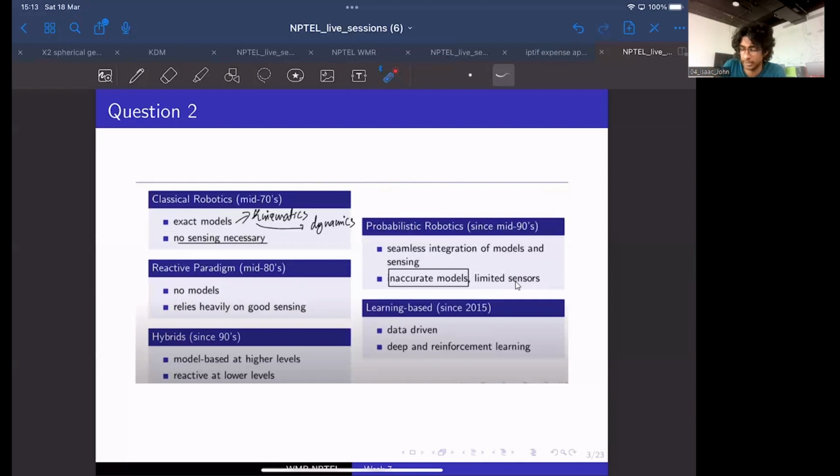So if we want the robot to follow a desired trajectory, and the robot is giving you an actual trajectory, there will be some differences between the desired and actual, right? The feedback from the robot is taken back so that it can be compared with the desired. The difference between the desired and actual trajectories is considered, so that further inputs can be given to the robot.